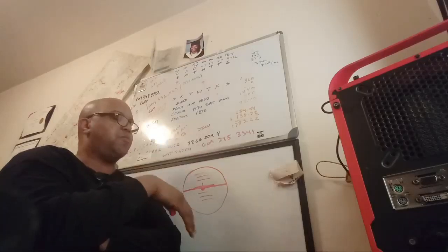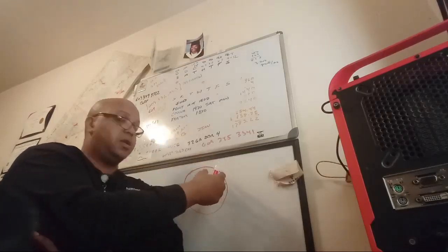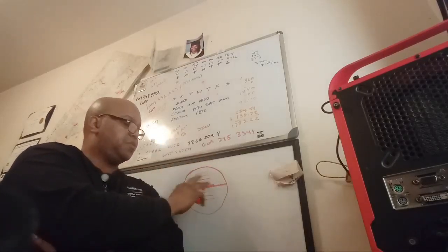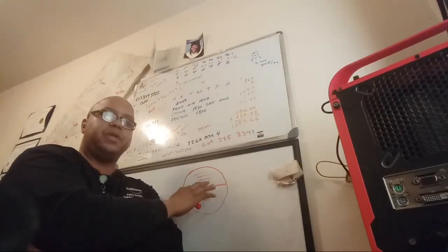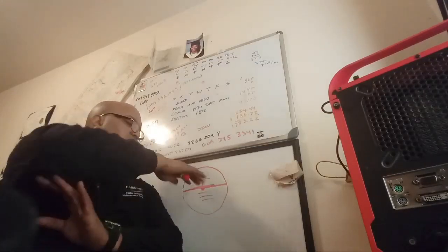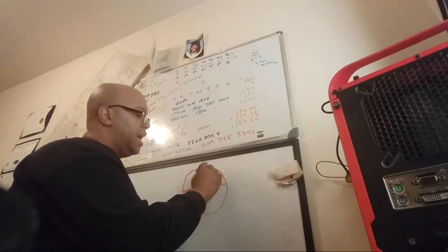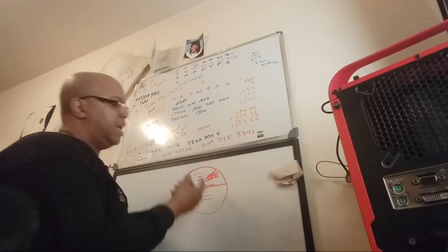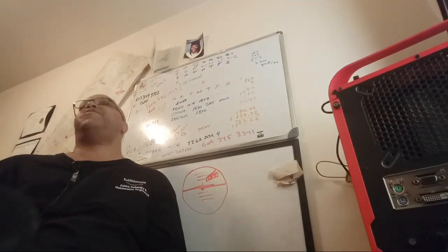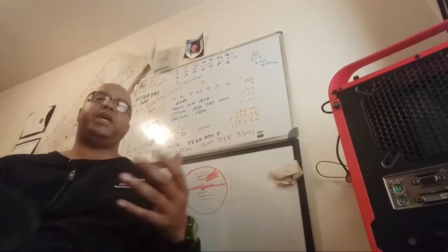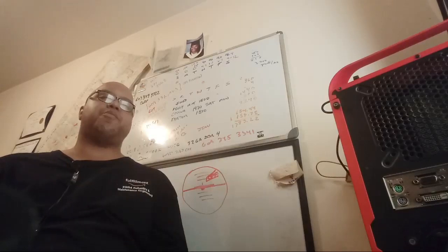So as long as you have vacuum pressure or suction, this thing should be nice and stable. If you're in level flight and this thing just starts to, sometimes you'll have a flag that will pop out here and say "off" to let you know that it is inoperative, meaning that we're not getting enough vacuum pressure.